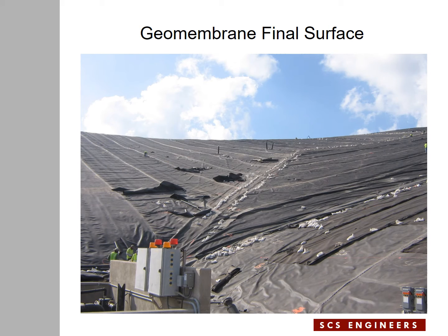Here, after completion of the geomembrane, is a picture from the bottom looking up, and on the two sides of this concave surface you can see the beginning of other slopes that run straight up and down on a 3-to-1 slope, and between these two lines is the area of the pie, the concave surface. And as you see, the geomembrane panels are intersecting along a line which you can refer to as a center line of the concave surface.